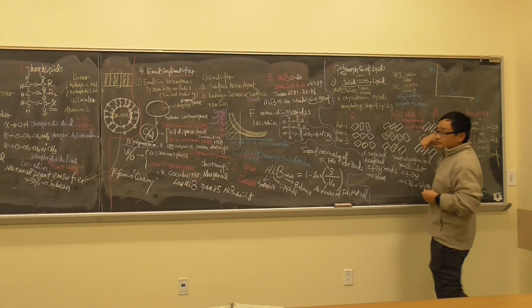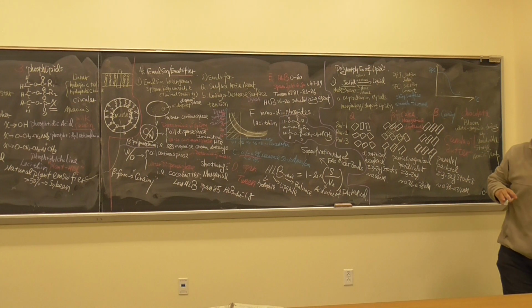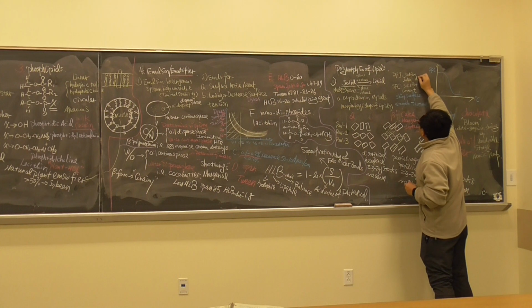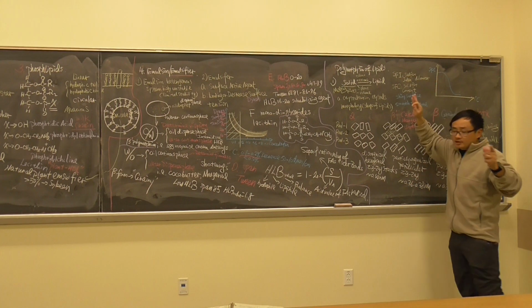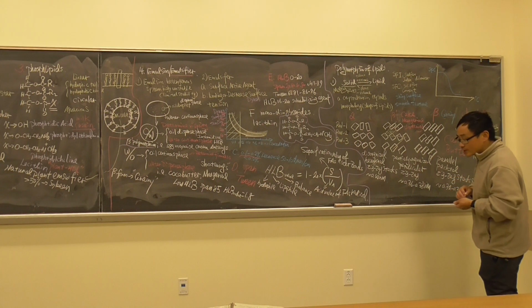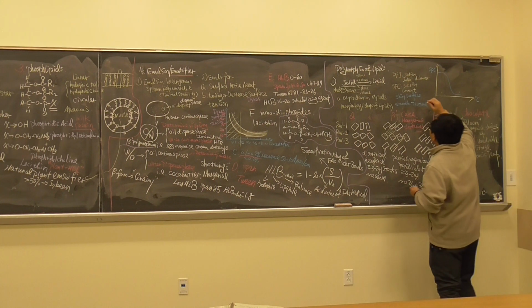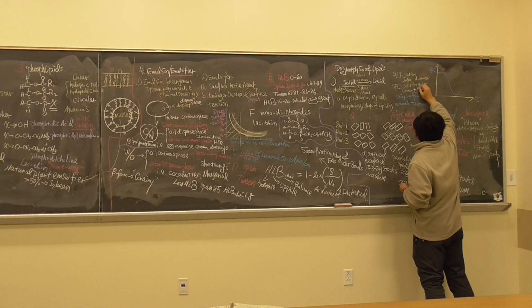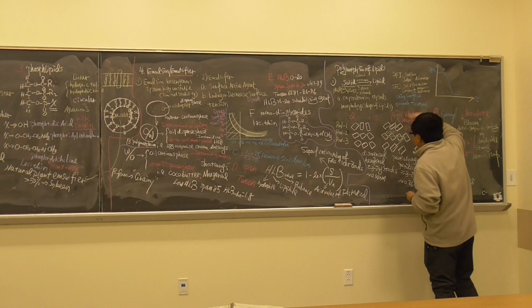What's the difference between them? Different measuring methods. SFI uses an older method, which we call a dilatometer. You just measure what dimension is expanded. With SFC, you see the exact solid fat content because you're using a nuclear magnetic resonance method.